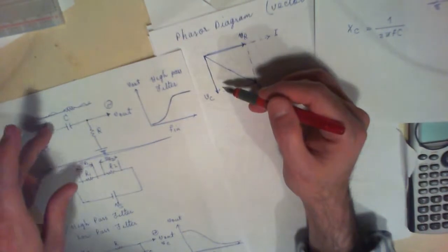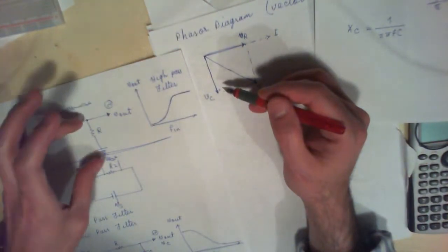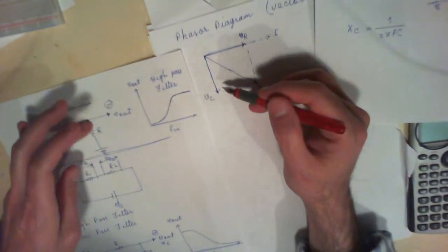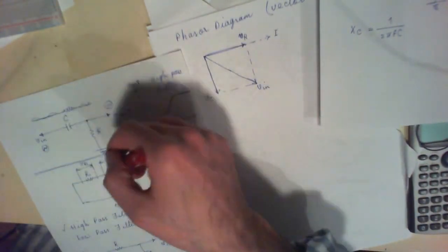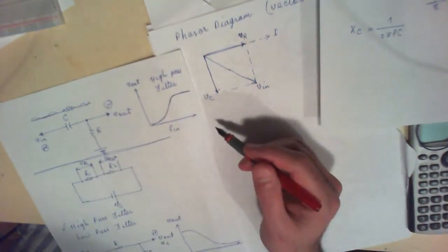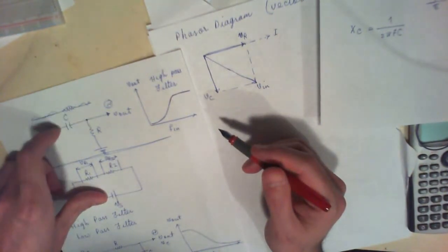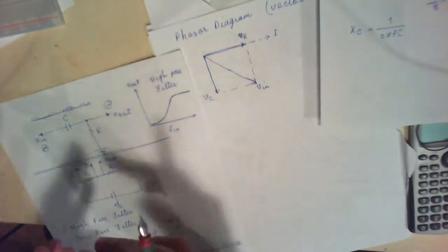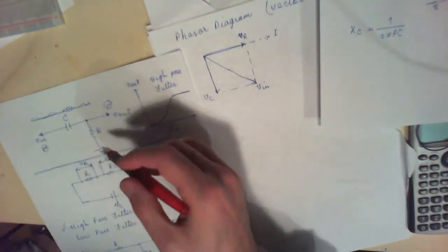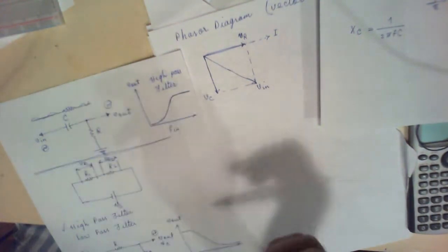That, of course, you cannot measure using an oscilloscope, because then you would ground your resistor and basically mess with the whole circuit. So I don't really know if it's possible to measure the voltage across this capacitor using an oscilloscope, because the two leads on an oscilloscope are basically grounded, so you cannot actually do that if you were to use both of your channels.